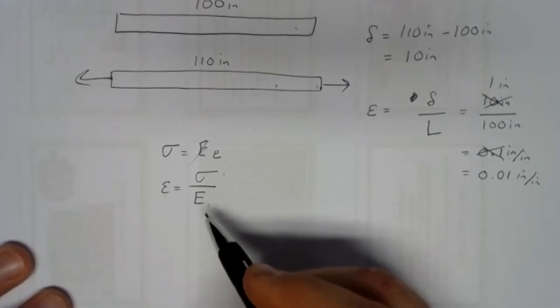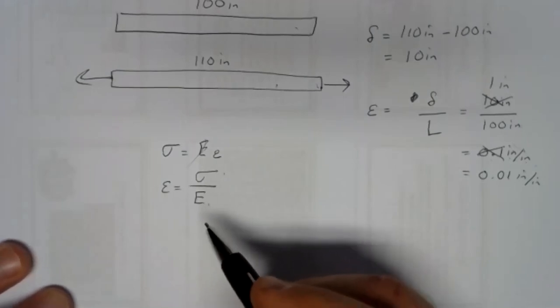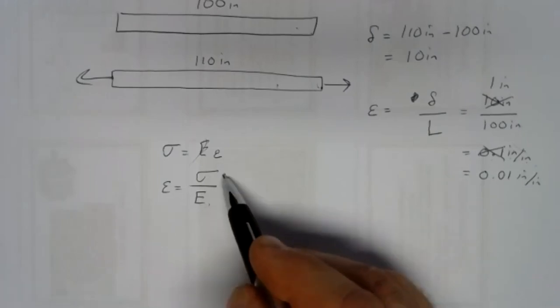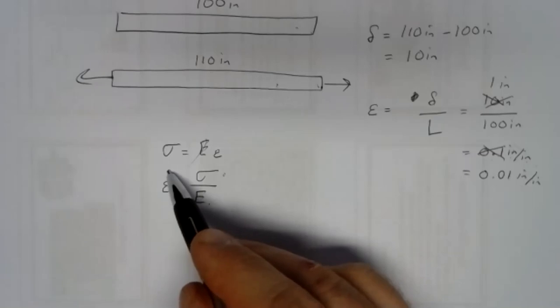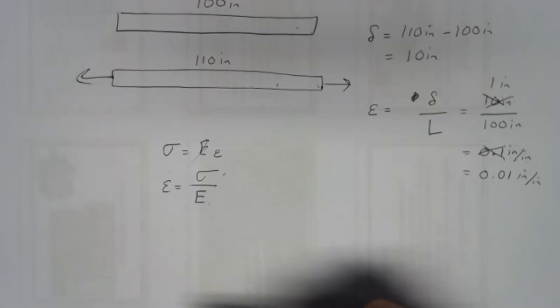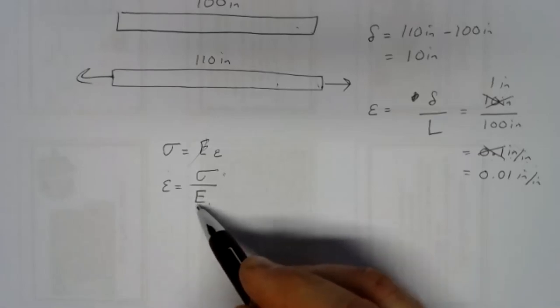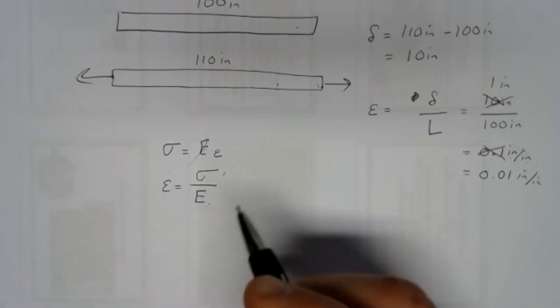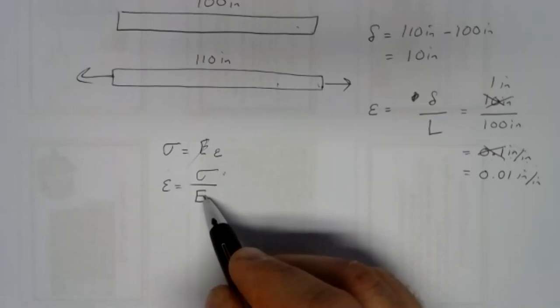Now, if we have a really stretchy material, a spring, something that's going to expand a lot, then that means we can put some stress on it and we'll get lots of strain. The Young's modulus for those materials tends to be fairly small. Things like rubber, for example, would tend to stretch out a lot. Elastic materials, they're not very stiff. So when Young's modulus is small, we have an elastic, stretchy material. When Young's modulus is big, that refers to a stiff material.